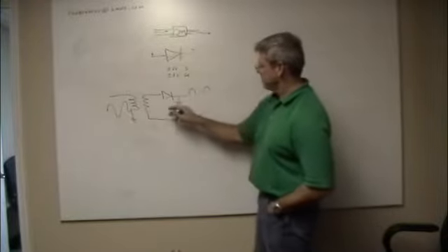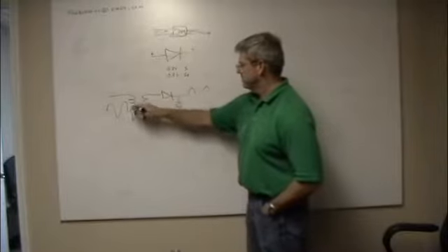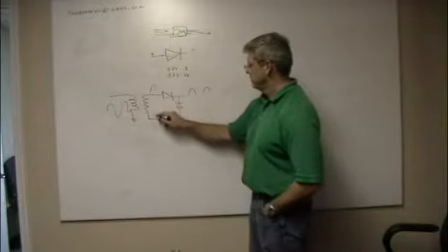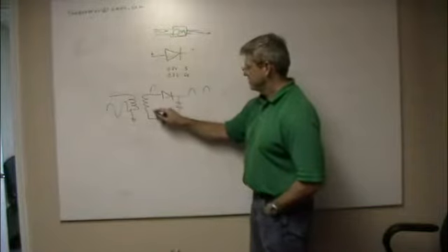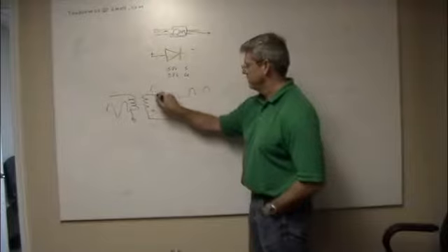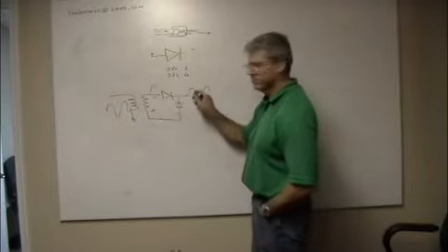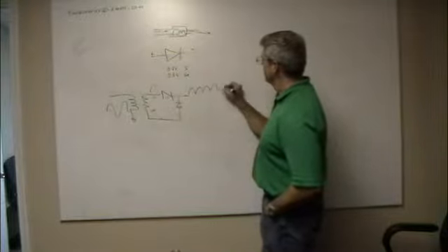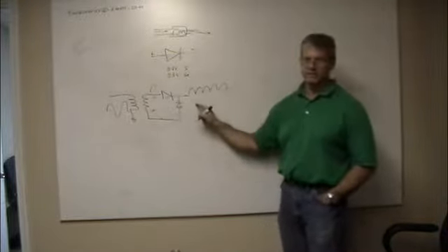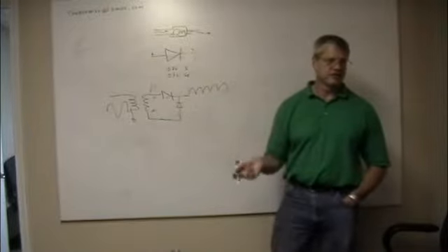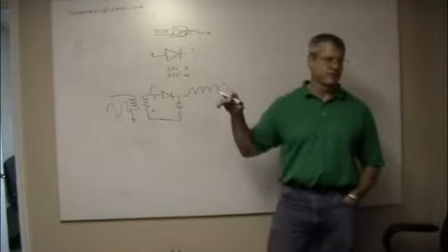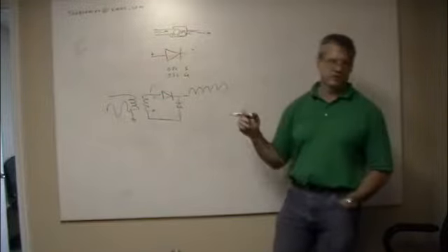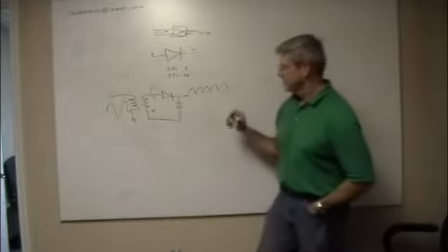This is a full wave rectifier. Now when this goes high, so when this goes positive, that goes through. When it goes negative, that's actually a positive voltage here and a negative voltage there. So current flows this way and comes up, and it can't go that way. So now you get a full wave rectifier. Practically speaking, you can use the same amount of capacitance but get less ripple, more power delivered, less power lost, things like that.